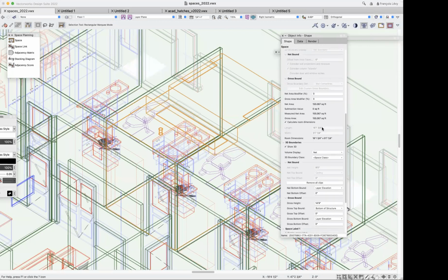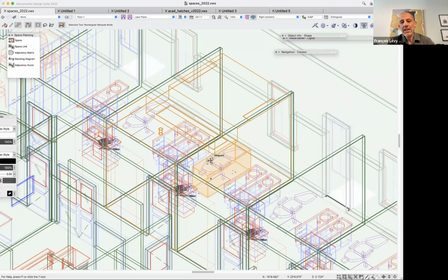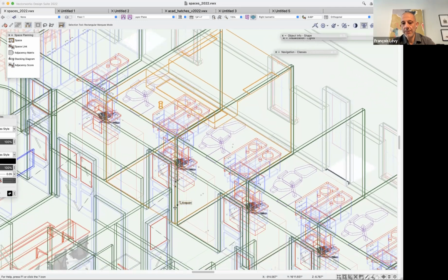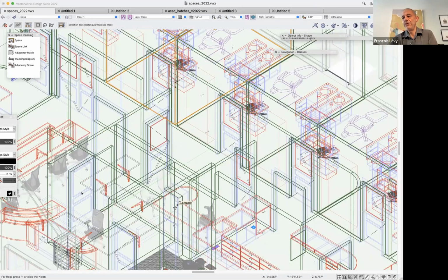What would be the need to create that niche for a space object in a doorway? Well, it's if there's just a slight change in volume. So that the space object, like if the window extends, you know, if the window is set in the wall and there's 3 or 4 inches of volume at the window, it would just add that volume to it. So that's the purpose of that. Its use would be for energy calculations if you wanted to be highly accurate with that.